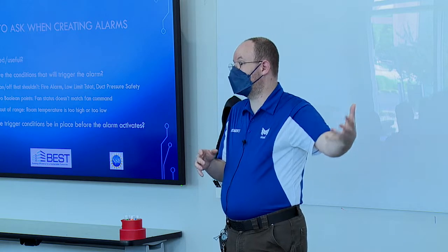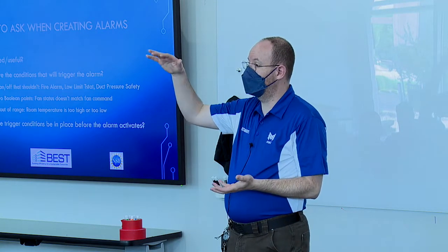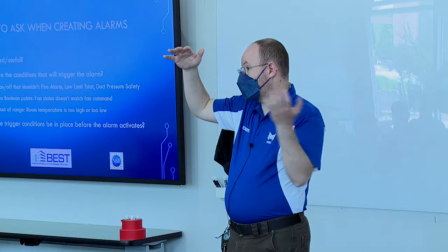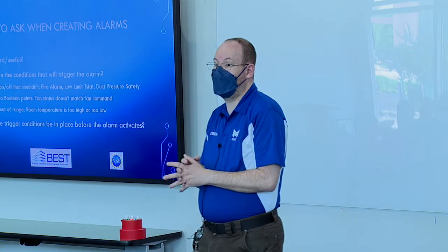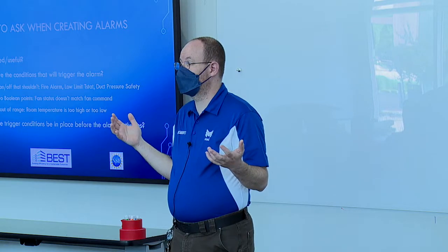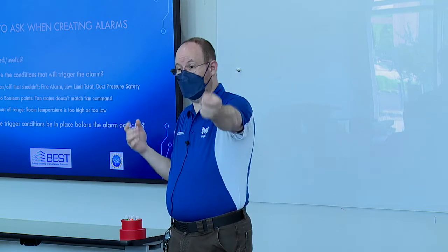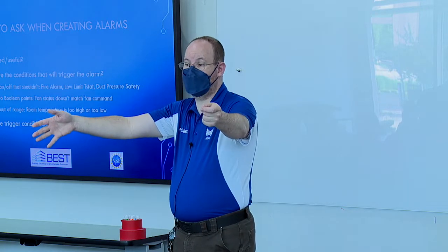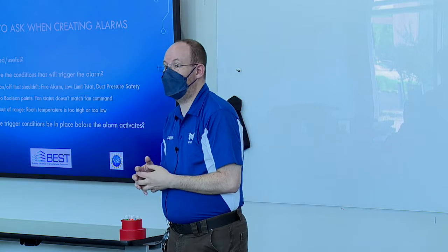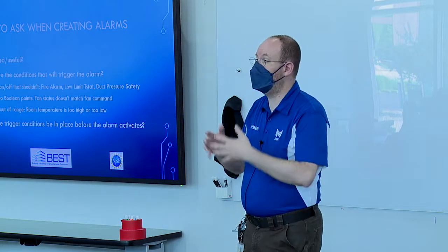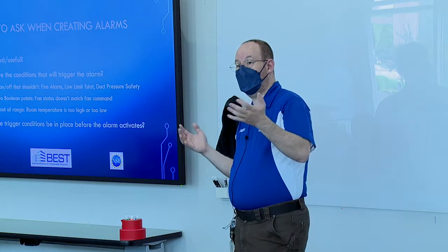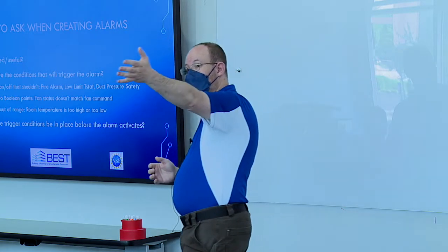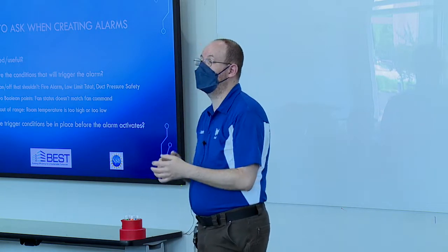Well, those electrical devices have to be tuned, and if it takes 60 seconds for your fan to ramp up, and that status donut doesn't turn on for 45 seconds, we turned it on, status isn't on, status isn't on, status isn't on. If we set that alarm right away, if we don't have that delay, then we end up with that nuisance alarm. And back to Russell's point of alarms that aren't set up properly.